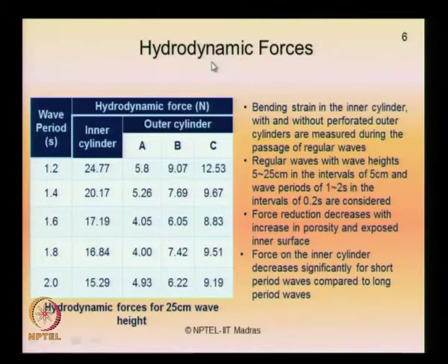Once we do this, the hydrodynamic forces on the inner cylinder, as I told you, are measured. The bending strain in the inner cylinder with and without covers is measured when the waves are passing the cylinders. Different regular waves with wave heights varying from 5 centimeter to 25 centimeter, and wave periods varying from 1 to 2 seconds at an interval of 0.2, have been considered in the investigation.